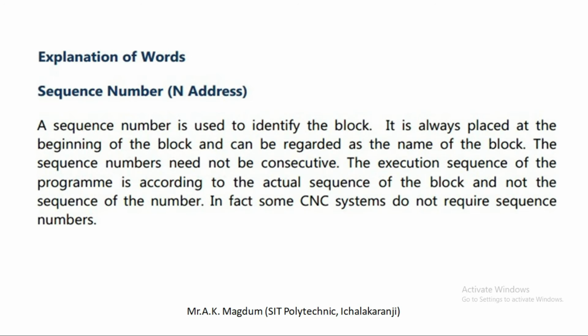It is always placed at the beginning of a block and can be regarded as the name of the block. The sequence numbers need not be consecutive. The execution sequence of the program is according to the actual sequence of the blocks and not the sequence of the numbers. That is very important.